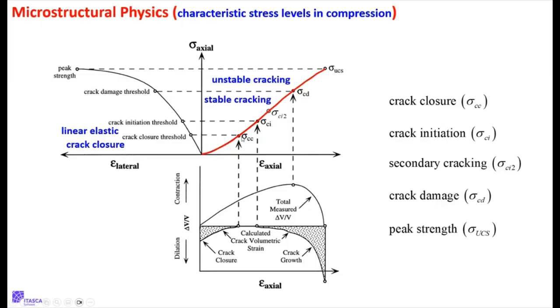They often just call those cracks, but they could be pores, all kinds of other stuff. You're closing those, and so it's getting stiffer. And now at this point, it's pretty much linear, which means you've closed them all. And so that's why this first part of the loading, they call it a crack closure stage. And once this is linear, they call that the crack closure stress. Okay.